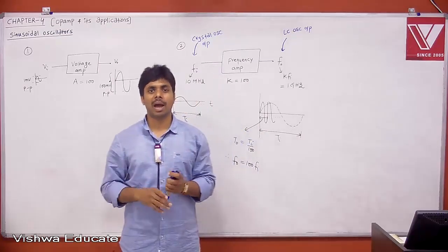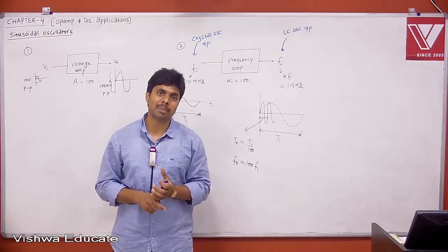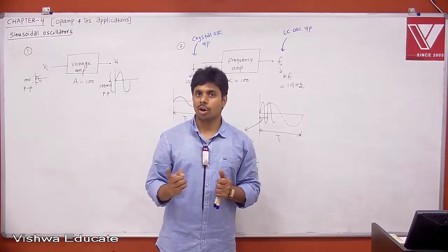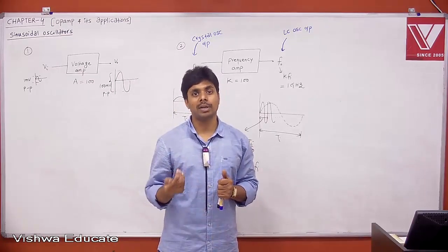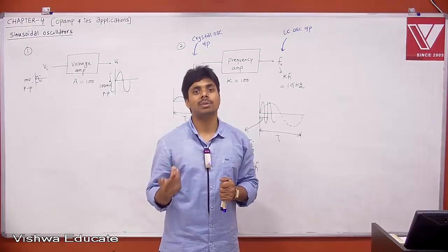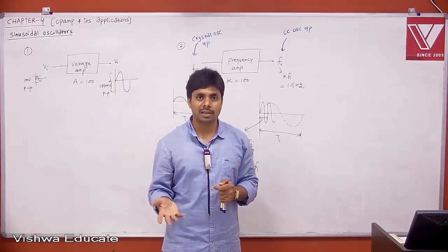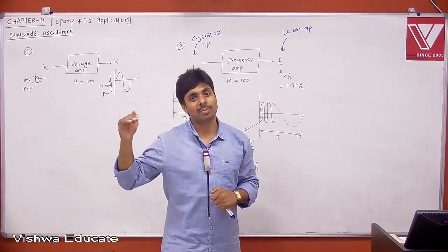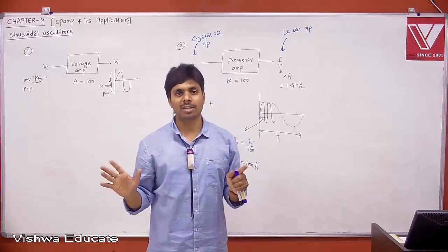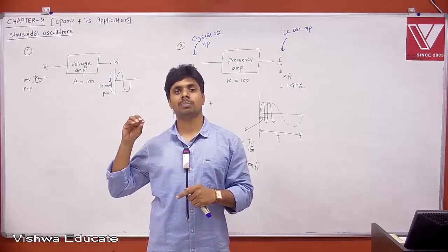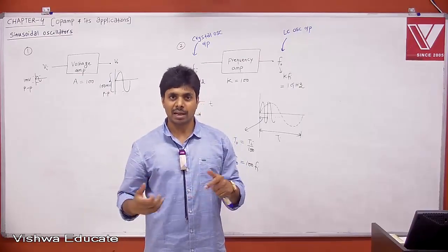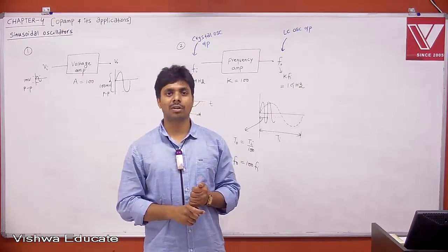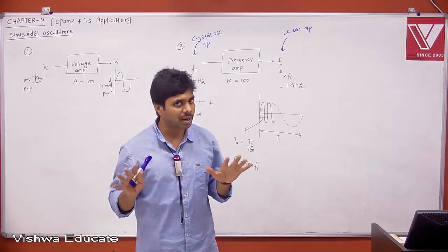Therefore, using negative feedback, we can stabilize any parameter: not only voltage gain, not only Q point or operating point, not only stability factor, not only current, power, frequency or power supply voltage. Anything can be stabilized using negative feedback, but corresponding feedback should be applied for the parameter you are concentrating on. Therefore, we can get stability. I hope everybody understood.